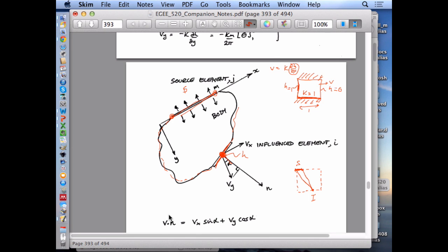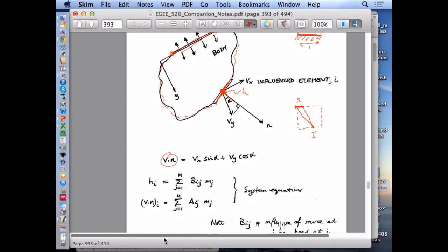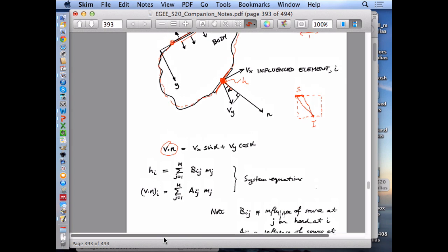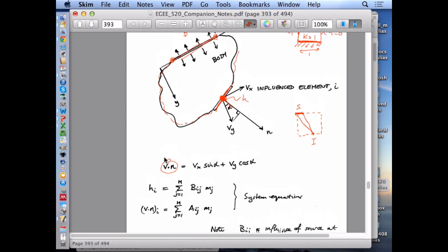So what we do is we use the dot product. The dot product of the velocity and the normal to the boundary vector just gives us the overall magnitude of the fluid that goes across that. We could show it, but I won't. You can just do it from basic vector algebra of the angles between the normal to the boundary and the actual x and y coordinates we have as direction cosines. These are direction cosines, and I guess this is the direction cosine of 90 minus alpha. Right? So that's that.